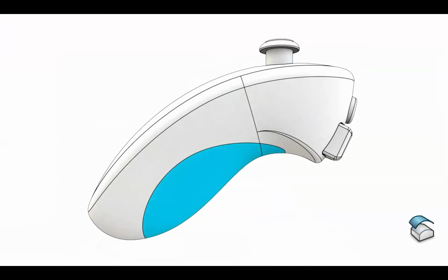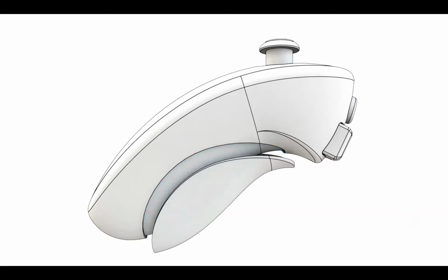To make an overmold, like in this case, thickening to intersect in slightly to make a pocket. So thickening as a cut, and then using the same surface to thicken geometry out. So you've got maybe the rubber overmold body as a separate body and the plastic housing. So it can be complex shapes to do the same thing.